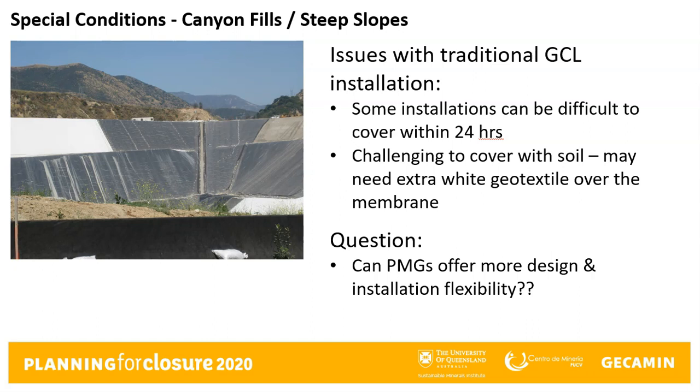So the intent of our work was to develop robust GCLs that don't require any special precautions to avoid desiccation. In addition, these products are designed to be used in a wide variety of cover soils that contain higher levels of calcium and be chemically resistant in the case of mining leachates and other leachates that are high in ionic strength.